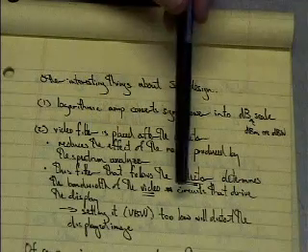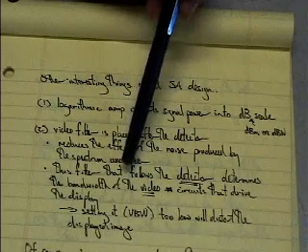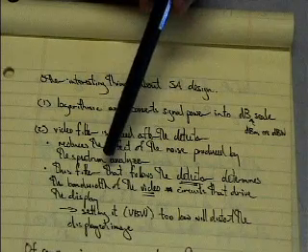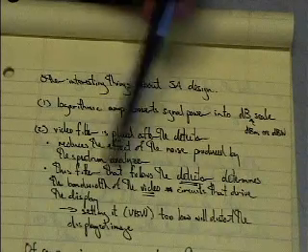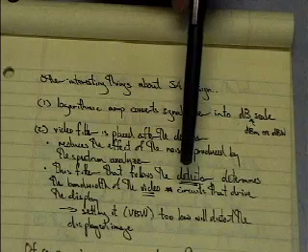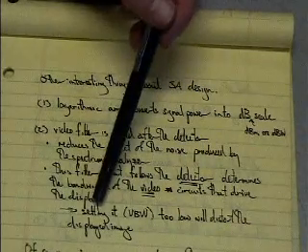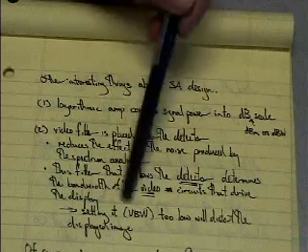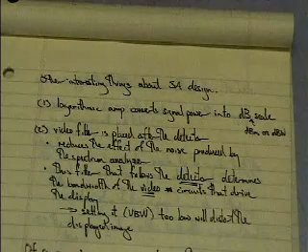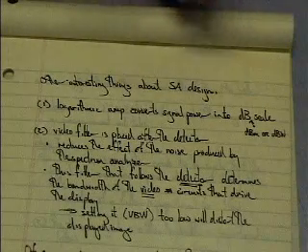But I guess the only downside is that you can use the video filter to a disadvantage. If you filter too much, you're going to really start distorting what your signal looks like, and you're going to get erroneous output. So basically in all our experiments, we're going to let the video filter be set automatically by the spectrum analyzer.